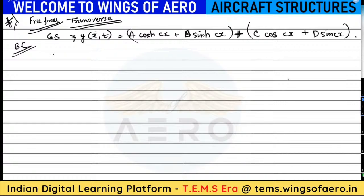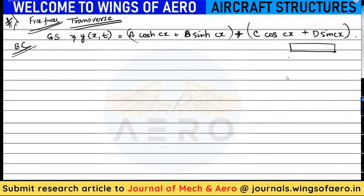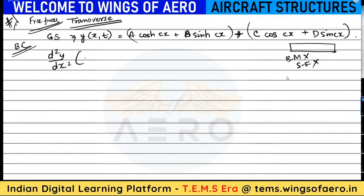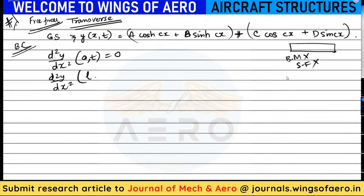Okay. Next. So for this, what is the boundary condition? Both the ends are free. So first of all, when both the ends are free, there will be no bending moment, no shear force. Bending moment, I know, is d square y by dx square. At the point x equal to 0, it is going to be 0. Now d square y by dx square, at x equal to the length, is also going to be 0.